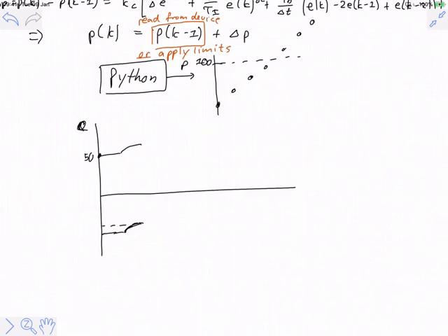There is no other difference. So if you have any discussion that says, well, the velocity form is better at calculating derivatives, or the velocity form does anything differently from the position form other than come away from limits faster, you've made a terrible mistake. That is wrong. And your group, if you're studying a group and that is what they said, that's also wrong.